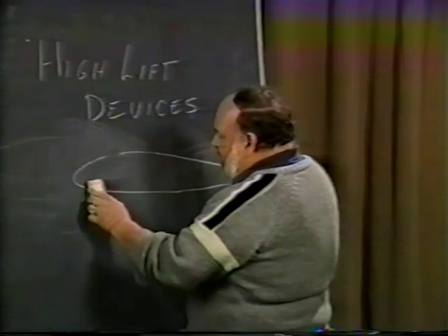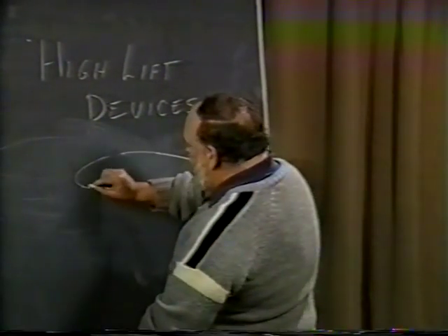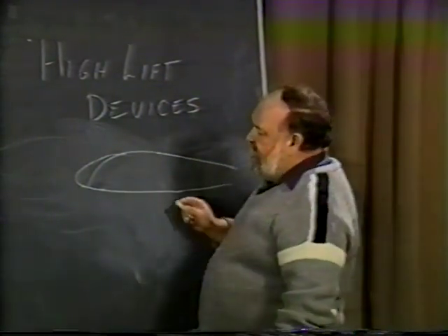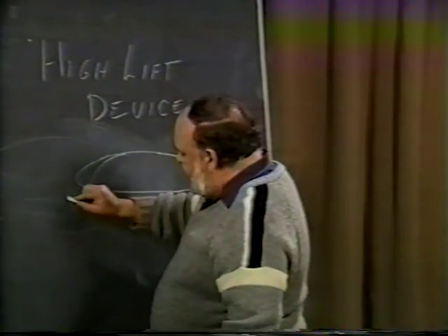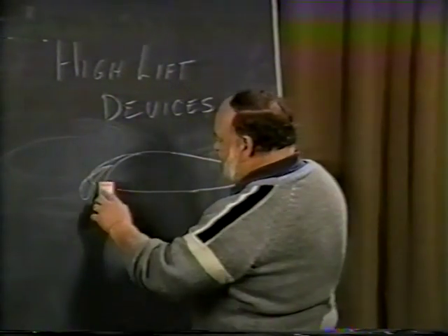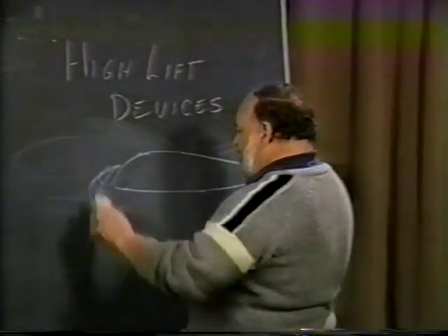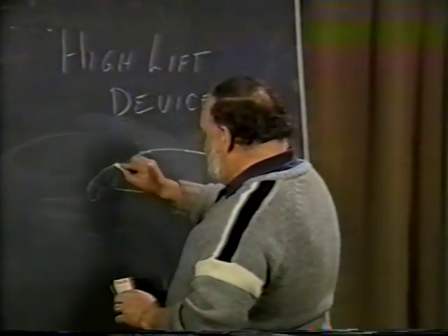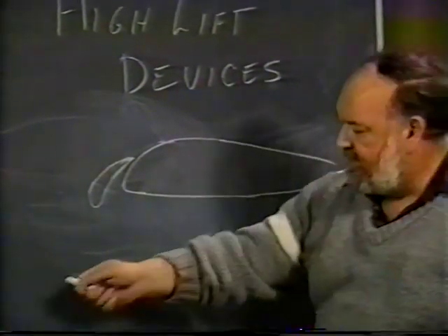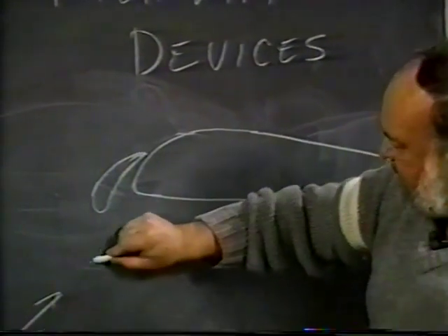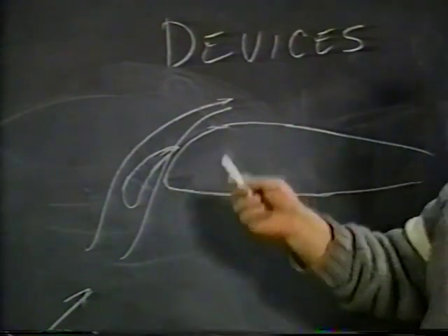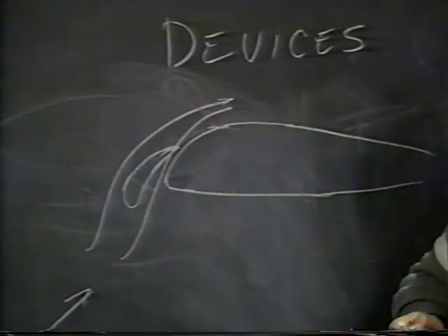Well, what is different? Well, you could go to an adjustable leading edge slot whereby the surface moves out on a track similar to that. Now you can see that you have just about the same advantage as you get to high angle of attack. As the air is flowing in this direction, it will then be vectored through this slot and up over the top of the wing, preventing the leading edge from stalling to a much, much higher angle of attack.